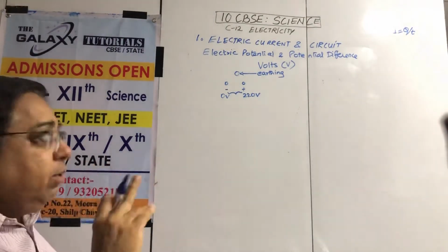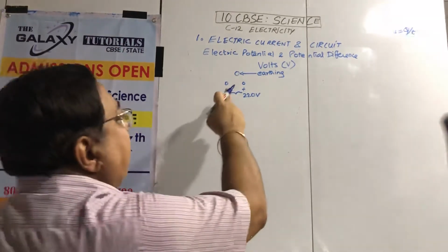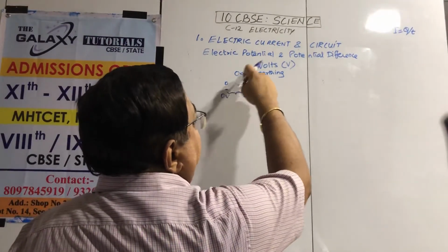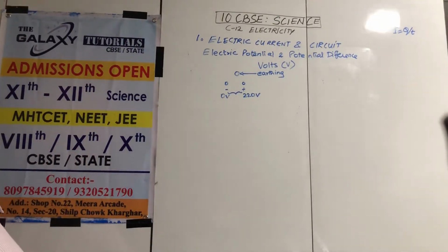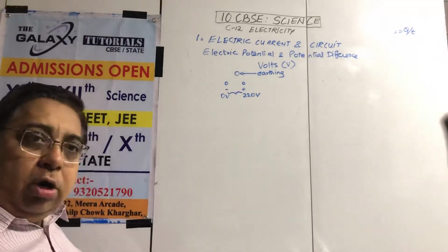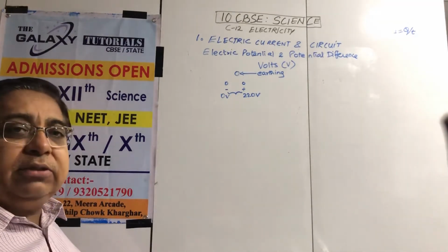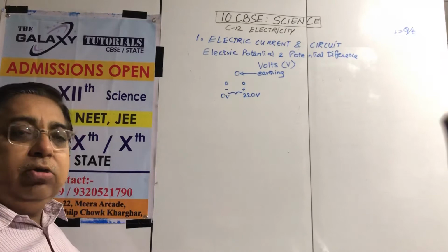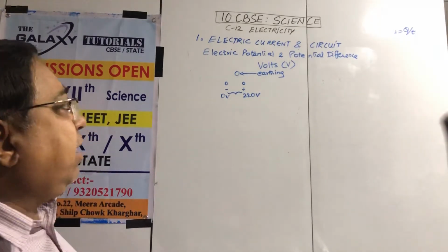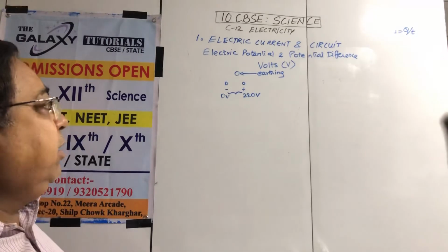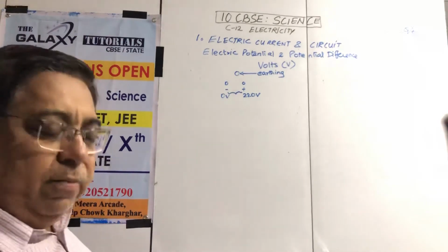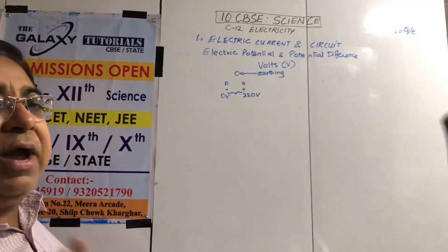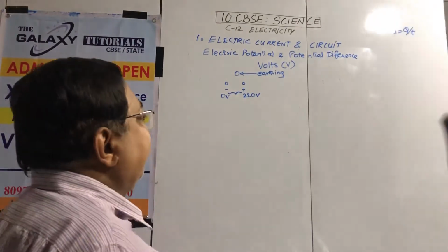Earth at the station. And as a bypass, suppose a wire breaks, we also have another wire which your electrician will connect to the earthing plate in your building or home at the ground floor. We make a pit, put coal, sand and salt, put water, make a solution, and then concretize it with this plate inside and wire going down. Because of the ions, it will conduct and the current will go away and save your life in case the negative wire broke and the current flows through your body. Now it will flow down, so you will only feel that somebody is touching your hand. So you know leakage is there.